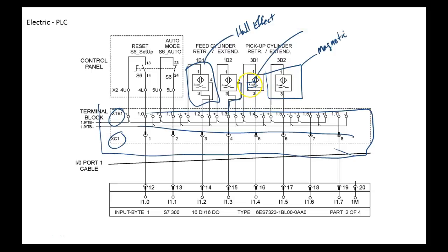See, they have this side of the magnet colored in and this side not. That's still magnetic. This only provides a normally open contact for us. So when it's false, the contact is open. When it's true, the contact is closed, right? Y'all understand that? You gonna go to sleep, Larry? I'm fine.